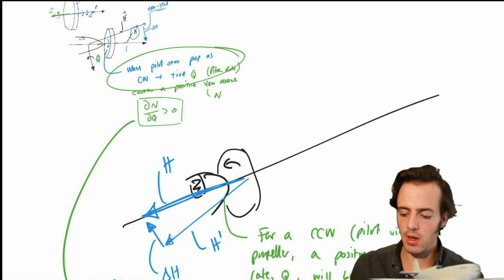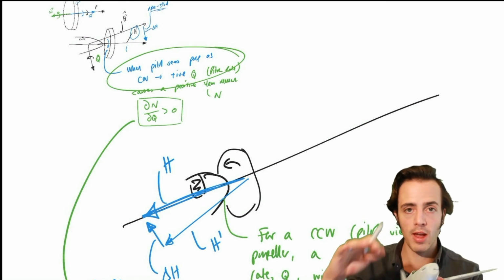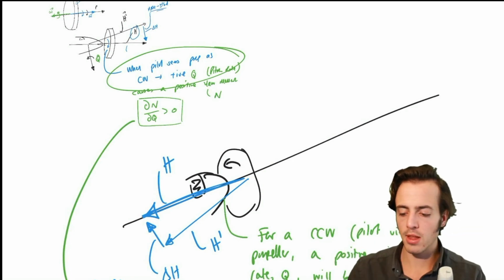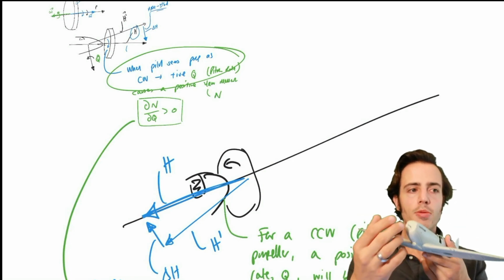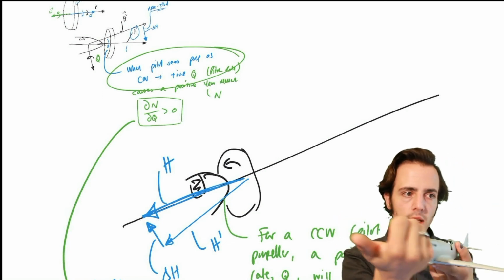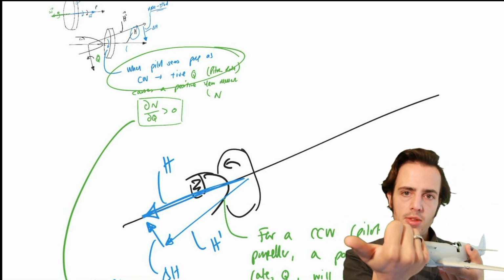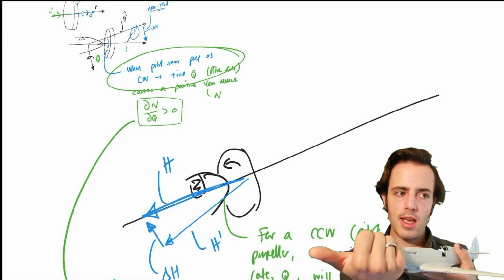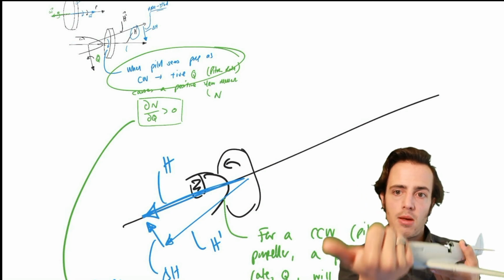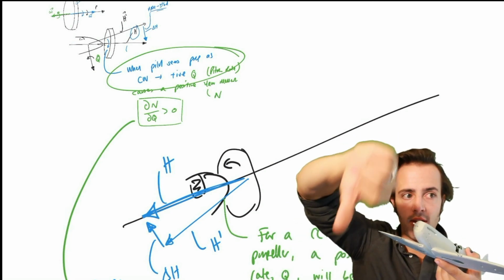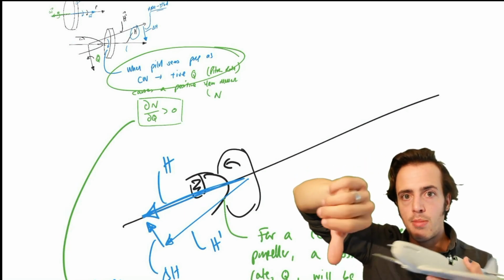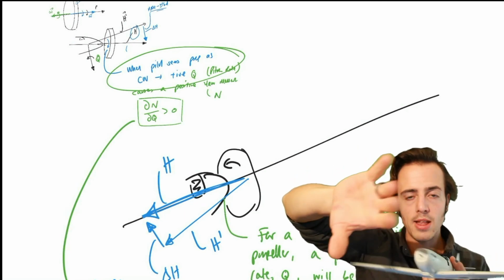And we then showed that the sign convention, i.e. which way it's going to yaw, is going to depend on the rotation sense of our propeller. So for a propeller that's rotating clockwise from the pilot's convention, our way of remembering this is I've got my thumb sticking out along the rotational axis. If the aircraft pitches up, to get my rotation vector h back to its original position, I've got to have a thumb going down. That's going to be a motion in that sense. So we have a motion which is this yaw rate, which is positive.